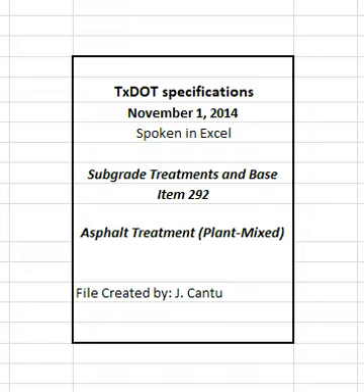4.2 Production operations. Produce a new trial batch when the plant or plant location is changed. Take corrective action and receive approval to proceed after any production suspension for non-compliance to the specification.